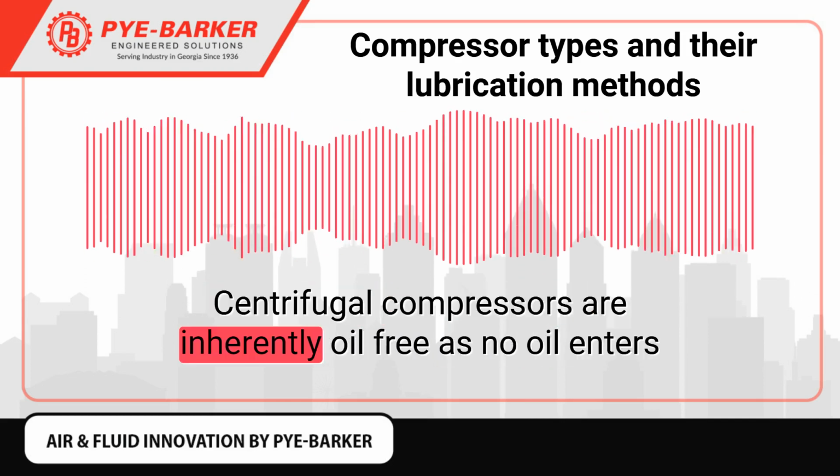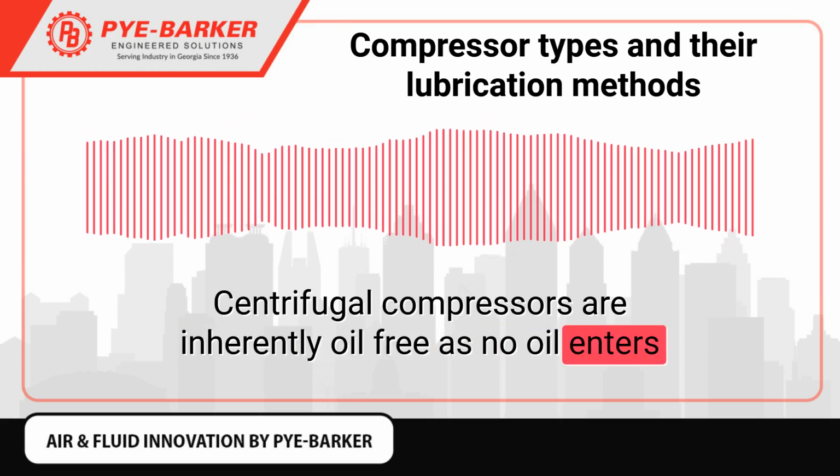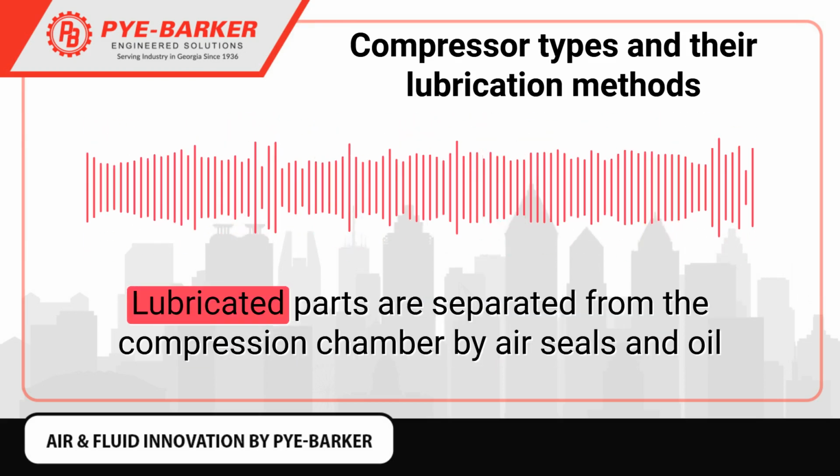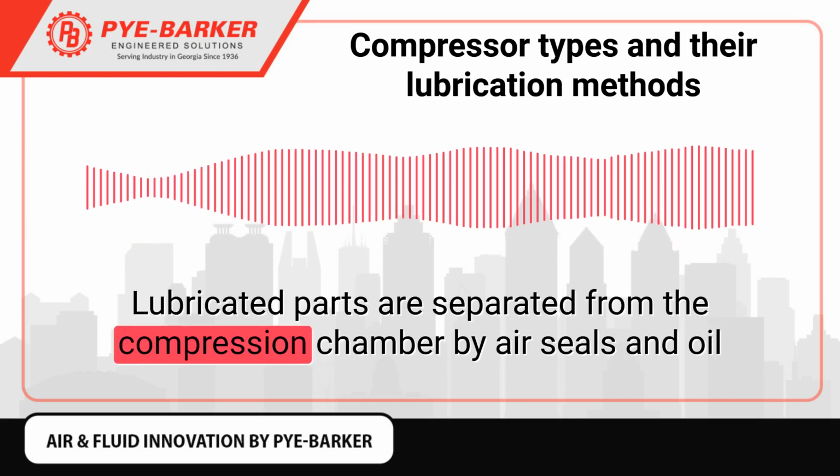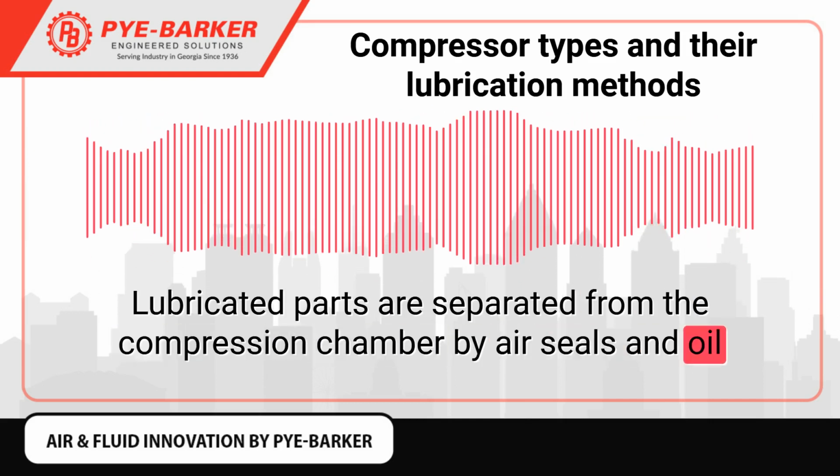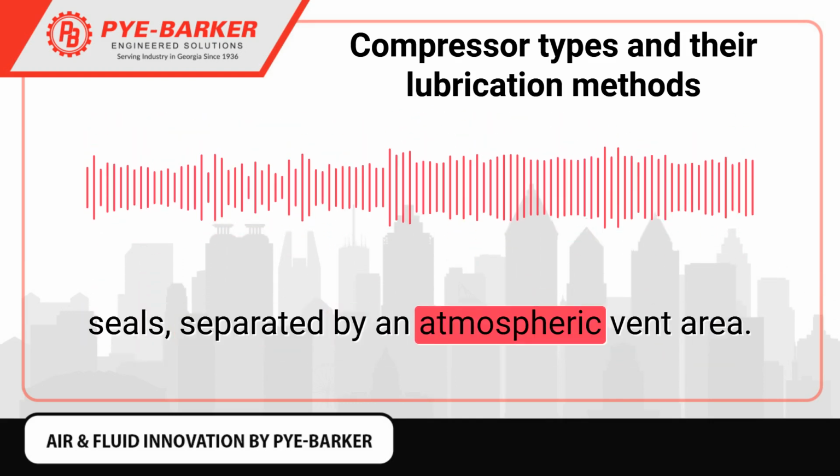Centrifugal compressors are inherently oil-free as no oil enters the compression chamber. Lubricated parts are separated from the compression chamber by air seals and oil seals, separated by an atmospheric vent area.